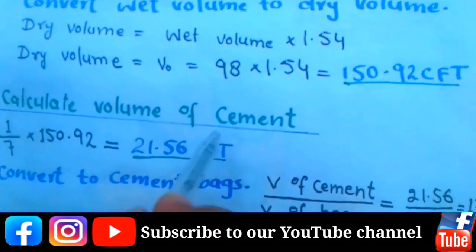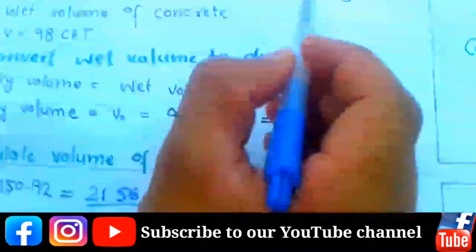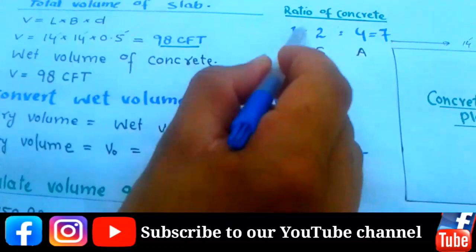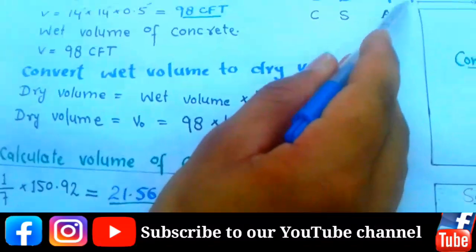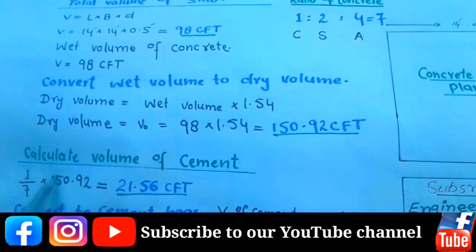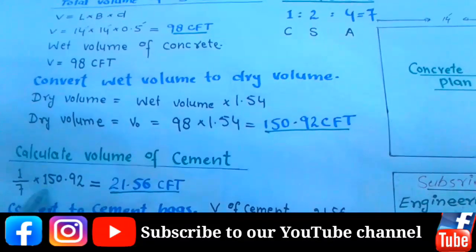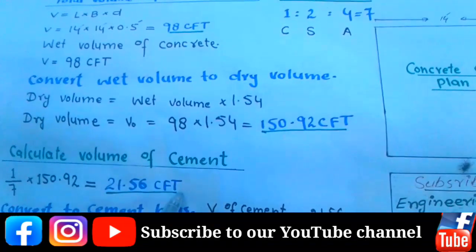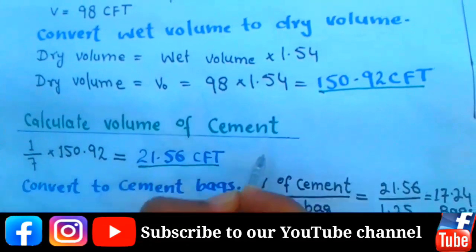First of all, we have to calculate the volume of the cement. So 1 is the value for cement in these ratios of concrete, out of the sum of these ratios. So 1 divided by 7 multiplied by 150.92, which is the total dry volume. When we multiply these, 21.56 CFT is found out, and this is the volume of cement for the slab.